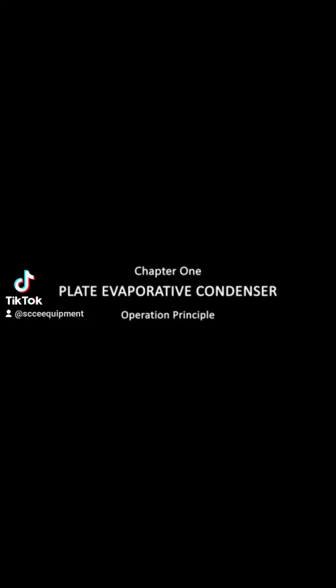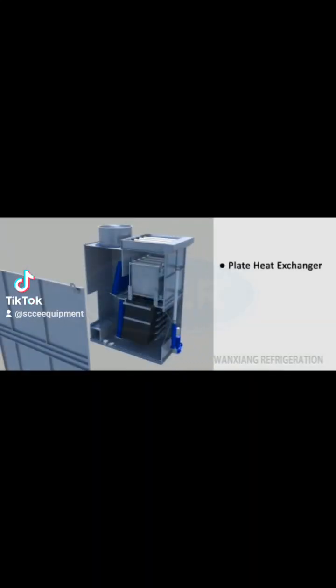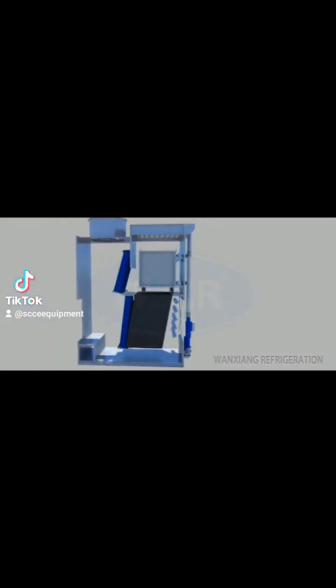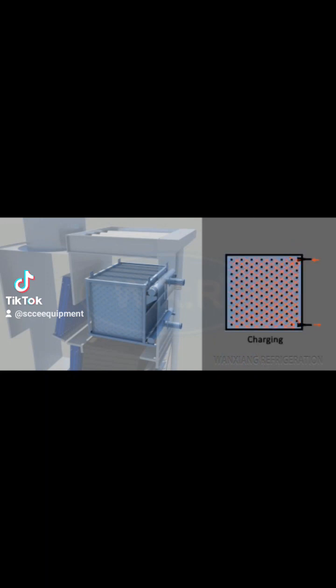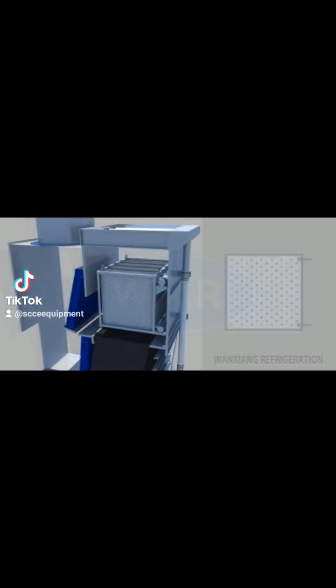Plate evaporative condenser consists of a plate-type heat exchanger, axial flow fan, circulating water pump, padding, and other auxiliary components. During operation, the high-temperature gas enters the channels between the two spot-welded plates, forming a single cassette, via the top header. The weld spots interrupt the gas flow intermittently, thus creating a turbulent flow pattern within the channels. This flow pattern does not exist in the conventional coil-type condenser.